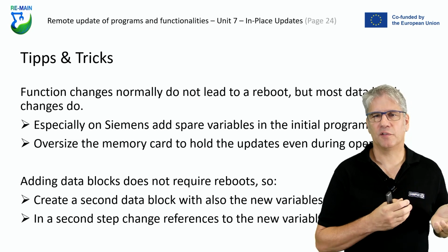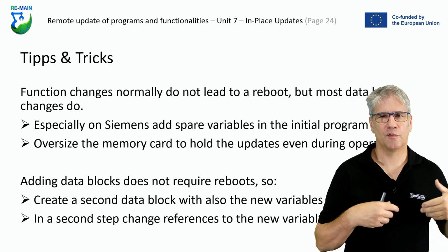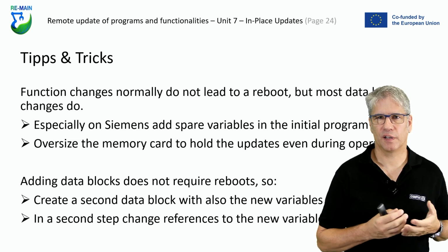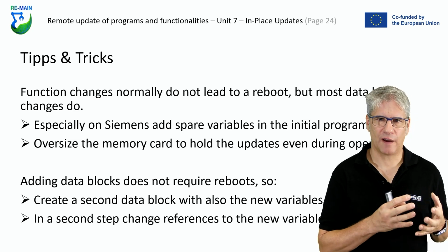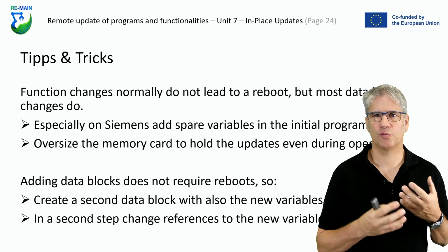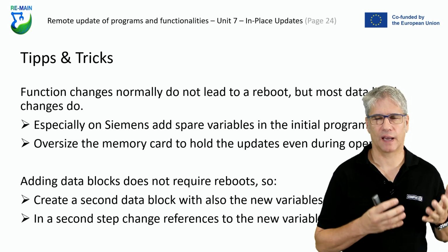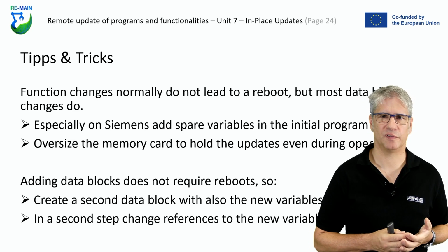Also, it is a good idea to oversize the memory card, so there's plenty of room for updates on the memory card, so you don't run into a memory error. And if you have to, for some reason, change only during operation, so a full download and a reset is not allowed for any reason.